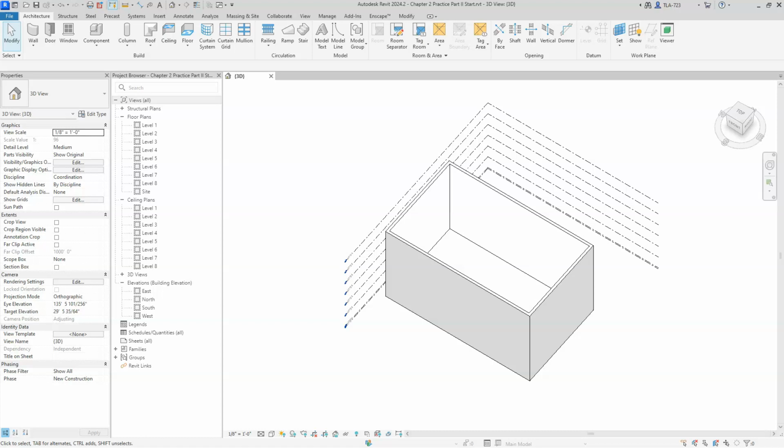It doesn't quite work as well the other way, going Revit into AutoCAD, but I think there is an export feature in Revit that makes that possible. But that's not usually part of the workflow. Normally, when we're going to be merging CAD files and Revit files, it's going to be the CAD file linked in or inserted into the Revit file.